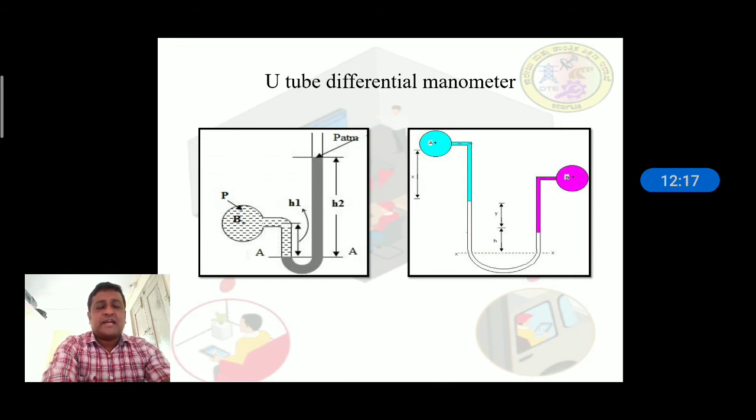Let us assume that the pressure we are measuring, applied to the left-hand side of the manometer, is of constant value. The liquid will only stop moving when the pressure exerted by the column of liquid, H, is sufficient to balance the pressure applied to the left side of the manometer. Therefore, the head pressure produced by the column H is equal to the pressure measured. This is the concept and principle we use to find the pressure in the U-tube manometer.